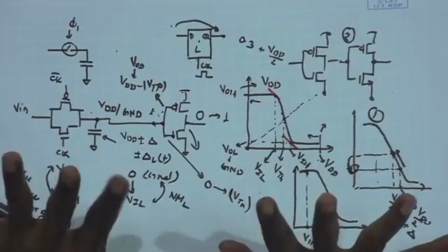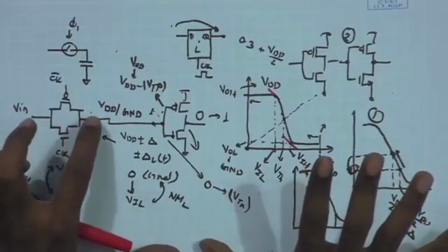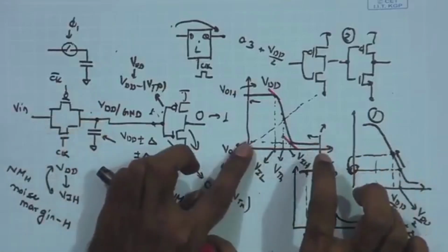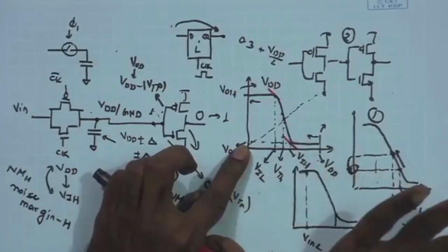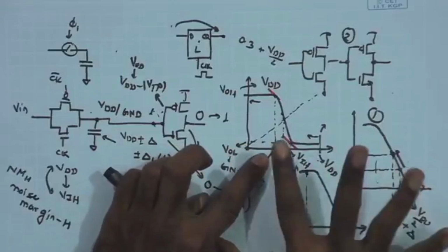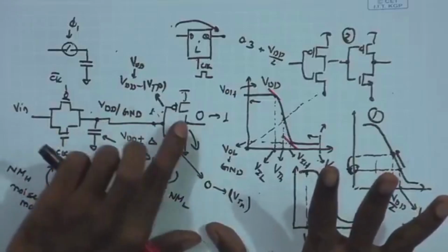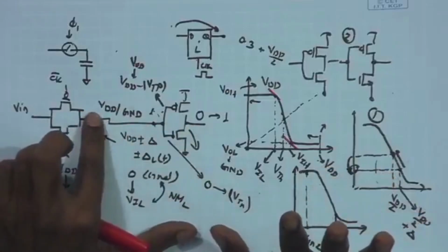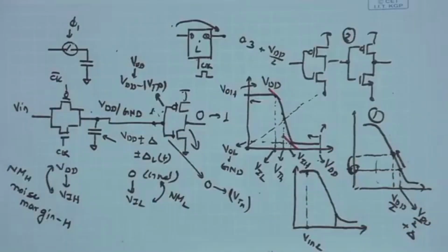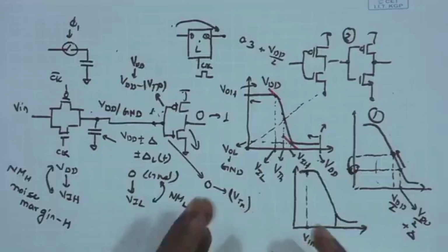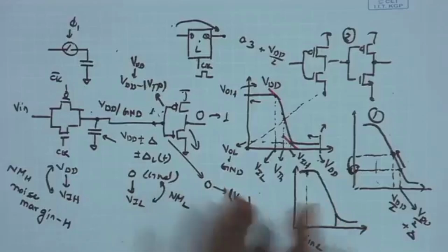preserving the logic level. So, what we are trying to say is, even though the voltage changes as compared to the original sample value by few hundreds of millivolt, that is your VTN or VTP, still the logic level is preserved. Still the next logic gate is treating this as high. So, you can see this is the reason why digital circuits are much more robust as compared to analog circuits. Analog, we have seen microvolt of noise can be a problem when you are processing the data at the front end, and we are very much concerned about the 1 upon f corner, white noise and so on.